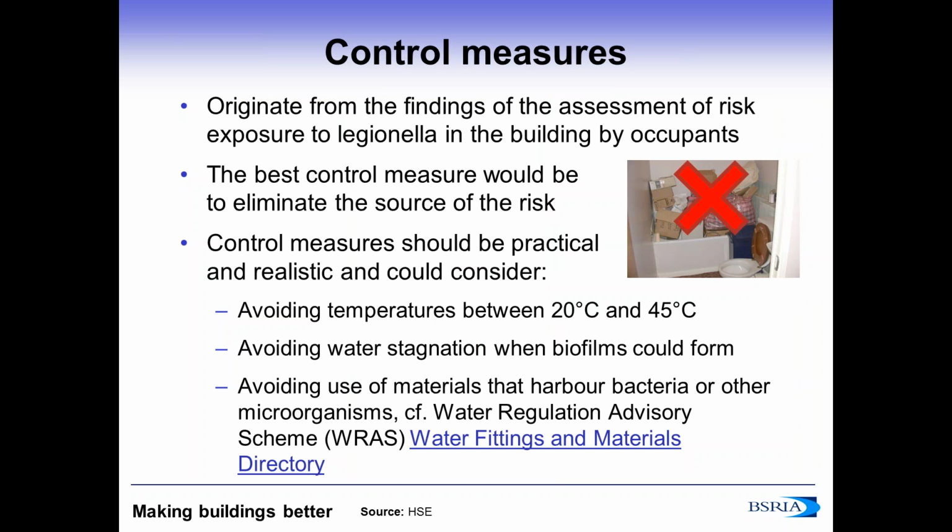It is important to understand that the control measures are derived from a risk assessment, and in some buildings, the risk assessment may not identify any risk for Legionella, and therefore no control measure will be required. For instance, a small building where occupants only use cold water directly supplied from the mains, without any water heating or storage facility. Too often, risk assessors forget that the best control measure remains to eliminate the source of a risk altogether. For instance, is the installation of a cooling tower the only solution to cool the air in your building? Do you really need this shower for the cyclist facility to achieve this additional BREEAM credit TRA 03?